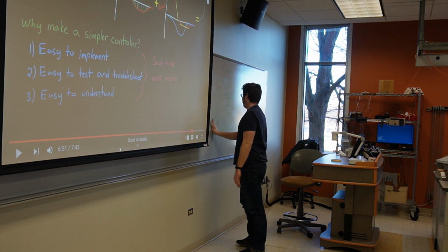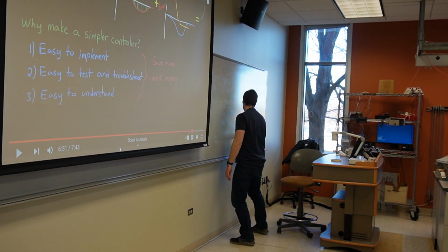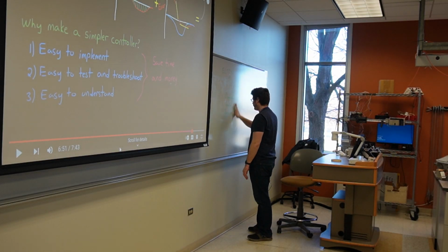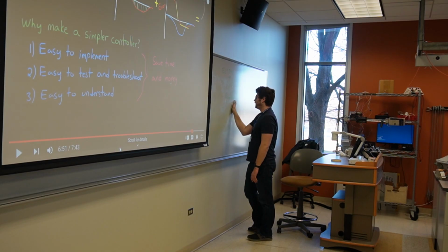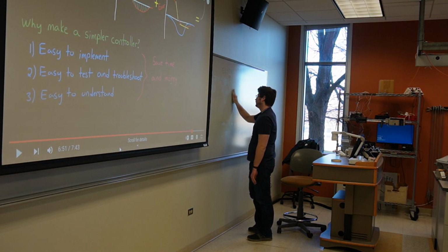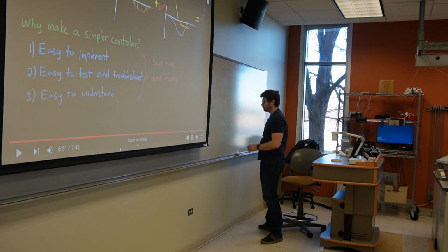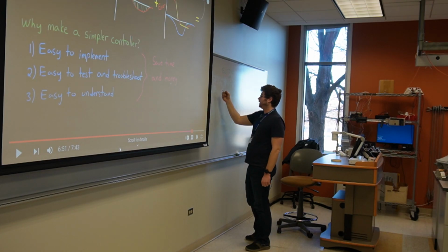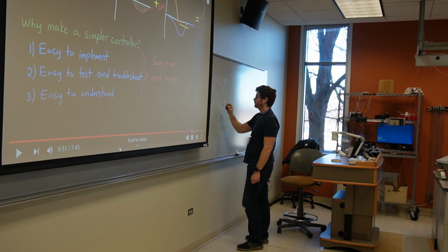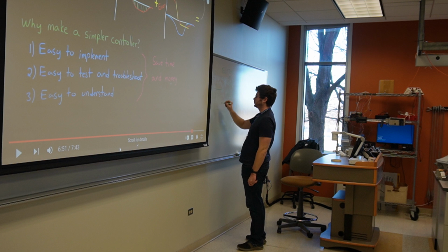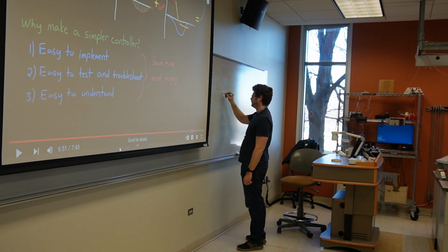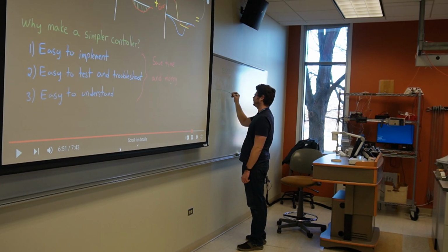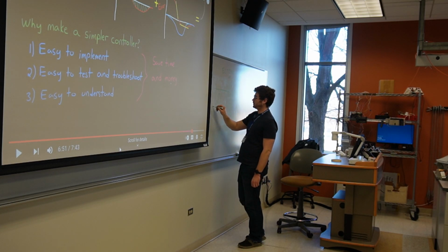All right, so a little bit more on this. Why exactly is PID desirable, especially in PLC land that we live in? It's really great because if we have a messy signal, for example, just a temperature controller, with ventilation going on, other heaters going on, whatever, it would normally be difficult.